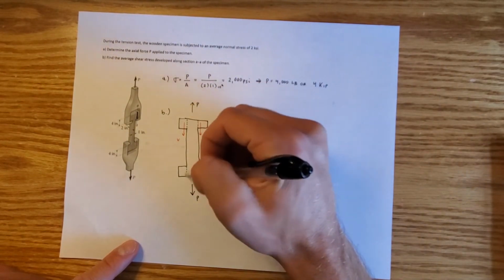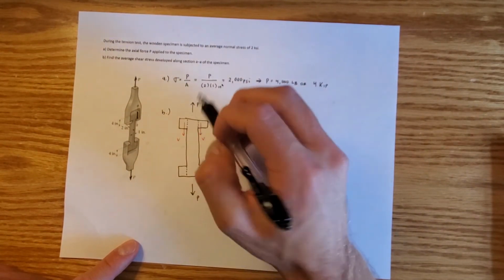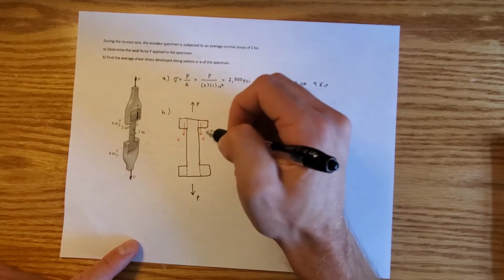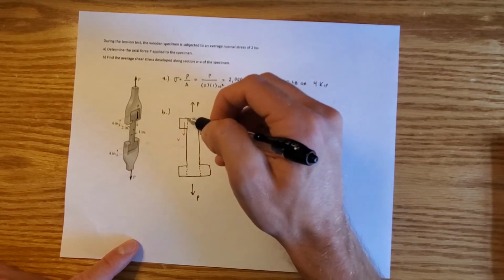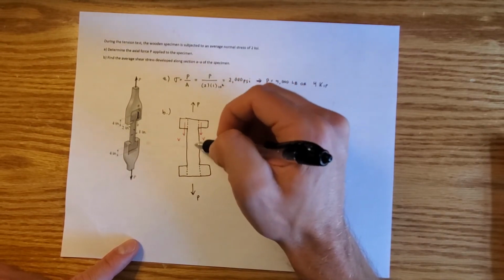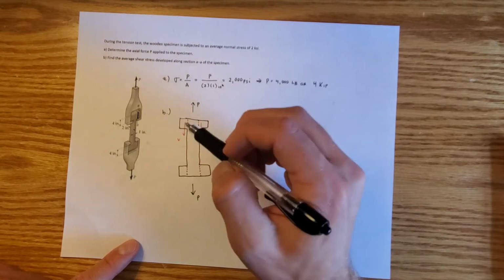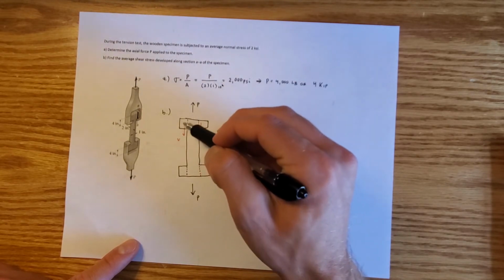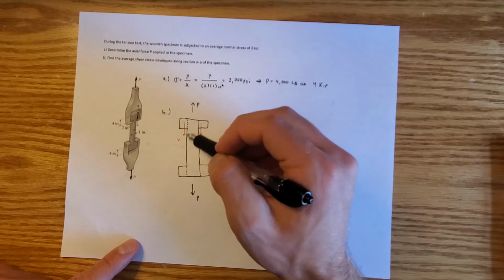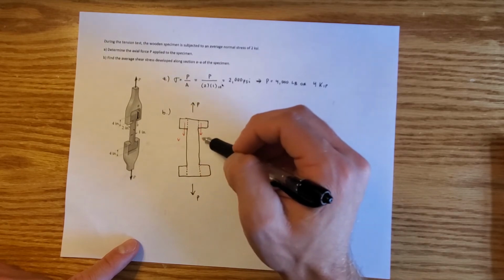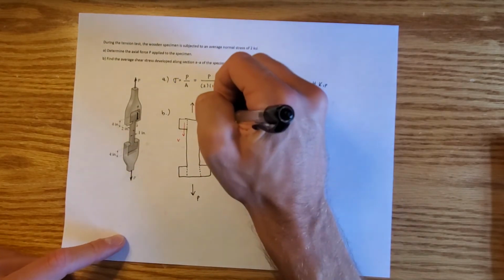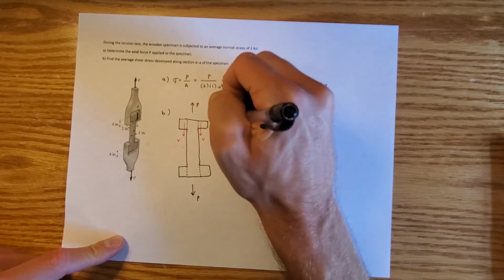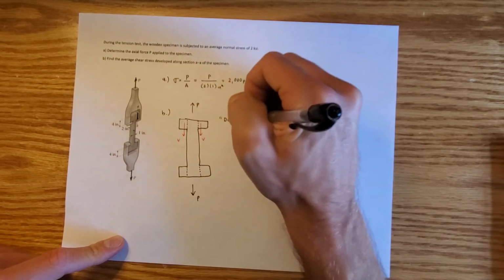And because the beam is held with these special grips here and it's in an eye shape, we can see that if this beam failed, this piece of wood would split on these two pieces right here, these two dotted lines. Because that's the case, that means we have two pieces of wood effectively that are fighting that, and we have two shear forces as reaction forces. This is, as we like to say, double shear.